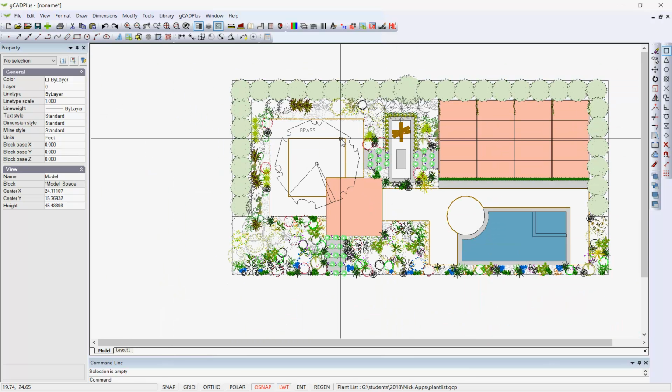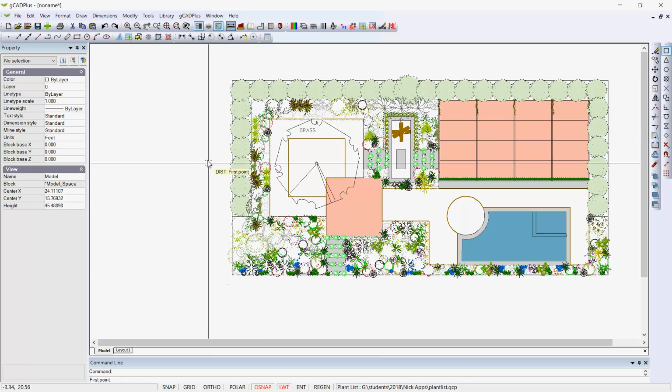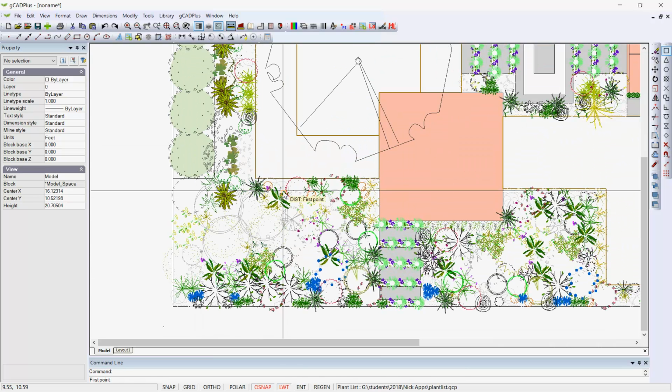So I hope that helps in understanding scaling and sizing. So to sum up, use your distance command to measure anything at all. The diameter of this symbol from there across to there is nearly 4 feet. It must have been scaled as it goes in, but all of these symbols have been either scaled up or down to create the sort of effect that we're interested in.